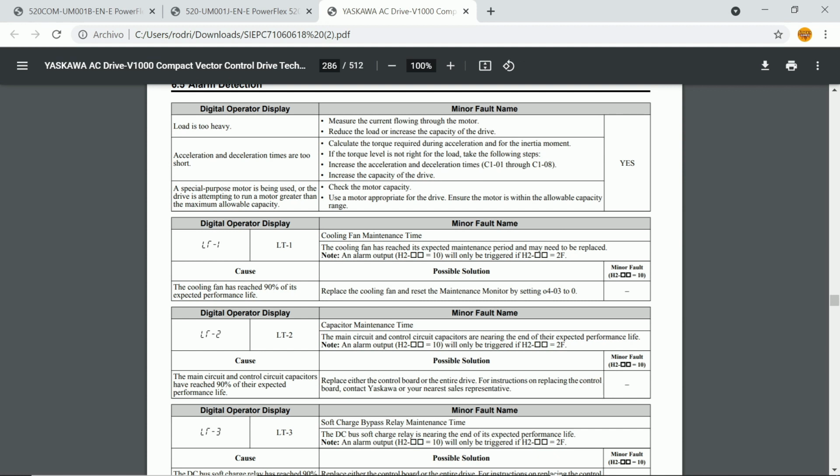Remember that we can do troubleshooting, and we put on our detective coat. We do our Sherlock Holmes work. We investigate. And so therefore, we should be able to investigate what the possible causes are. If it's stopped, then open the drive and see if there's an alarm triggered. If there is no alarm triggered, or if there's no fault, any sort of code, then in that case, something caused it to stop.